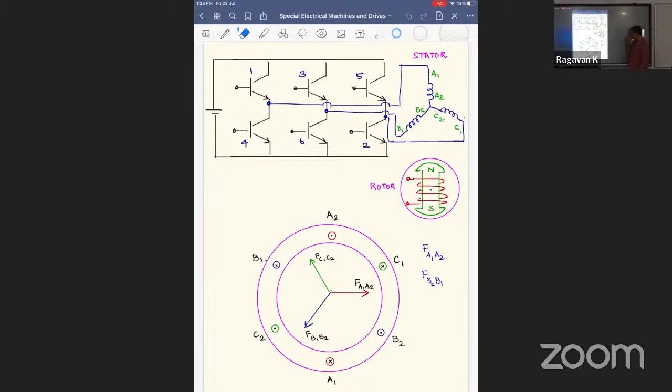Brushless DC motor. What we are doing is energizing one winding with a constant current. When I say constant current, this is a dot, this is a cross. The resulting MMF vector, because of this excitation, will be pointing like this, right? So all the time, quasi-square current, I said, let's say 5 ampere. I don't know, what ampere will Anshul be doing? 1 ampere, fine. So what he will be giving is 1 ampere constant, 0, minus 1 ampere.